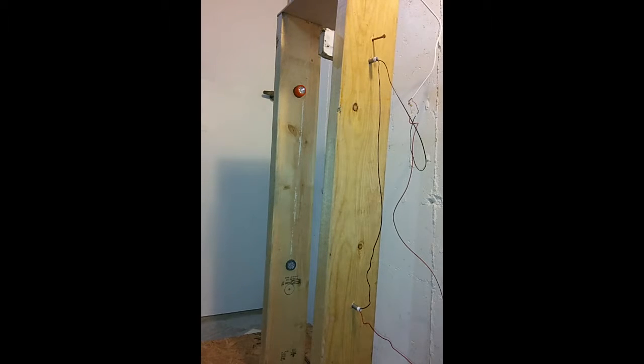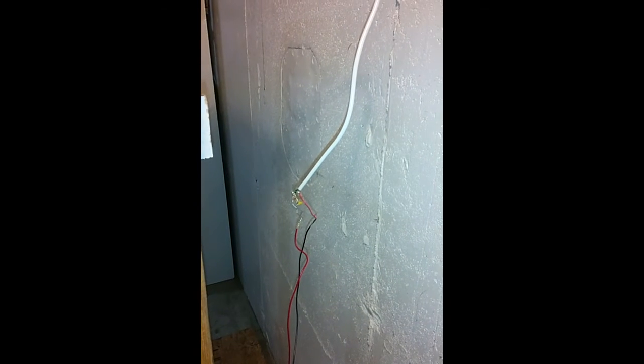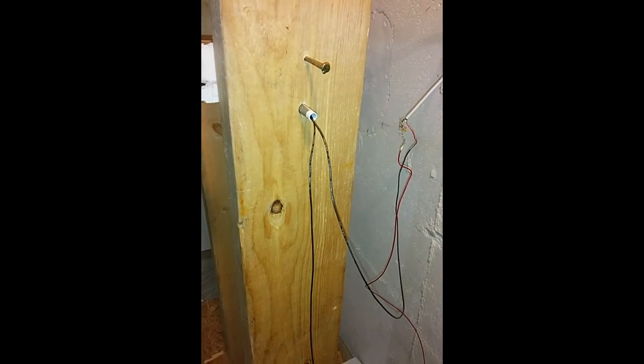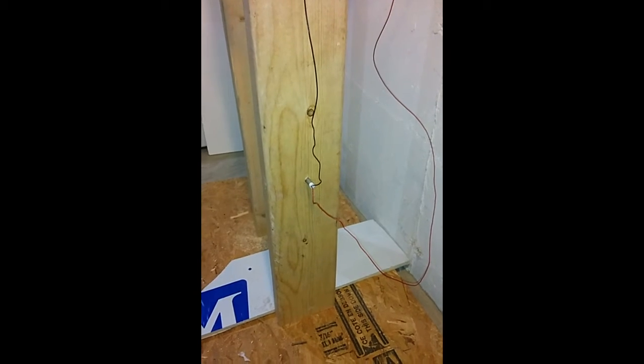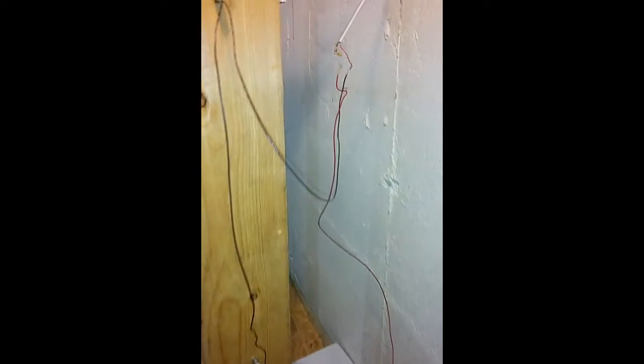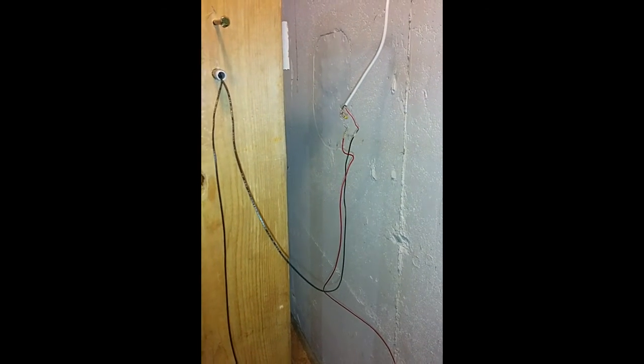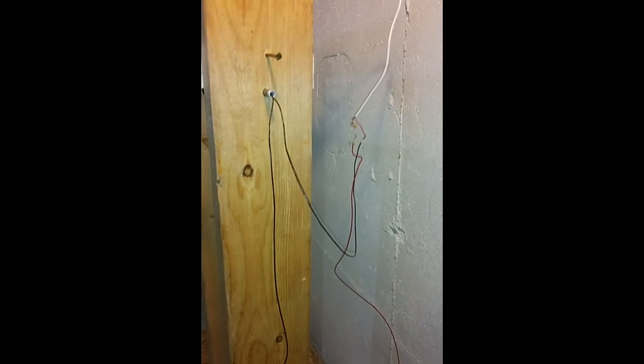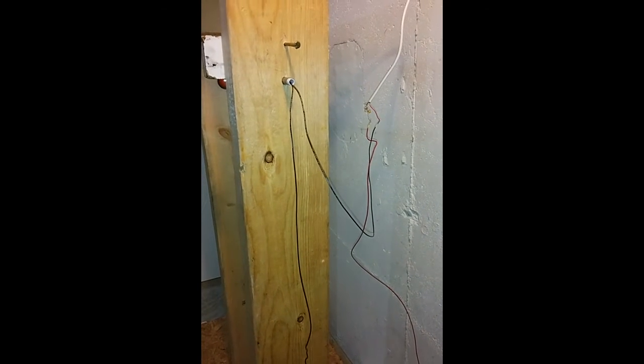We're going to attempt to time an object falling 1/2 meter using this photoresistor network and circuit and the GateTiming app. The circuit that we're using is here, and it's connected to the speakers, running through the first photoresistor, which is connected to the second photoresistor, which comes back to the circuit on the microphone side. Now, the first thing we have to do is calibrate this circuit and the lighting conditions that we have.